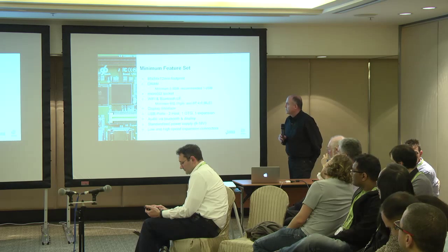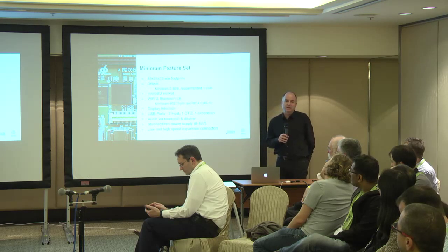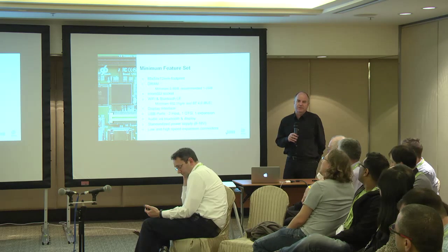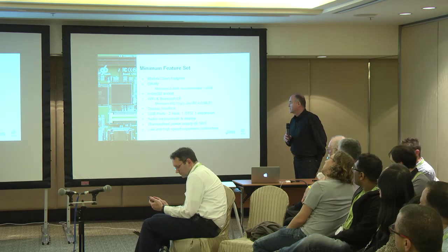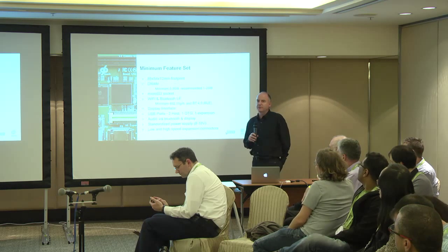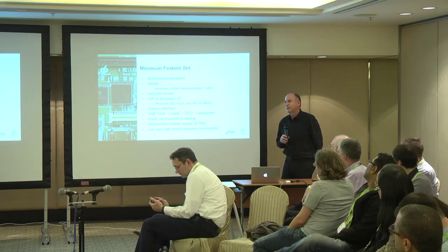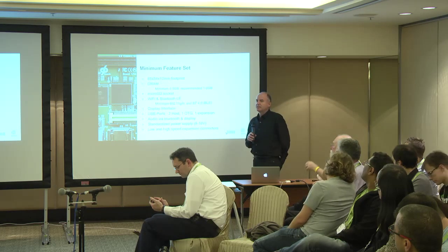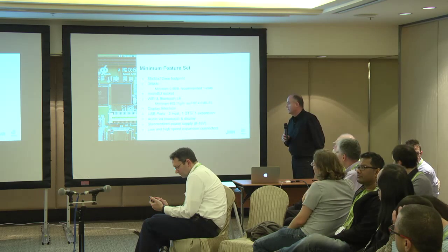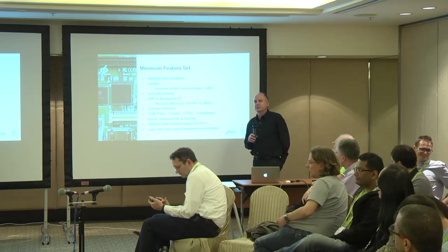USB ports, I'll come to in a few minutes. Audio, the minimum requirements are audio via Bluetooth and via the display. Putting additional audio onto the board, for example stereo jacks, is optional. Standardized power supply: we really wanted to make this thing powerable from USB. But when you look at some of the SoCs that are around today, 8-core A53s, they tend to use a fair amount of power when they're going at full usage, and you just don't get enough power off a micro USB.